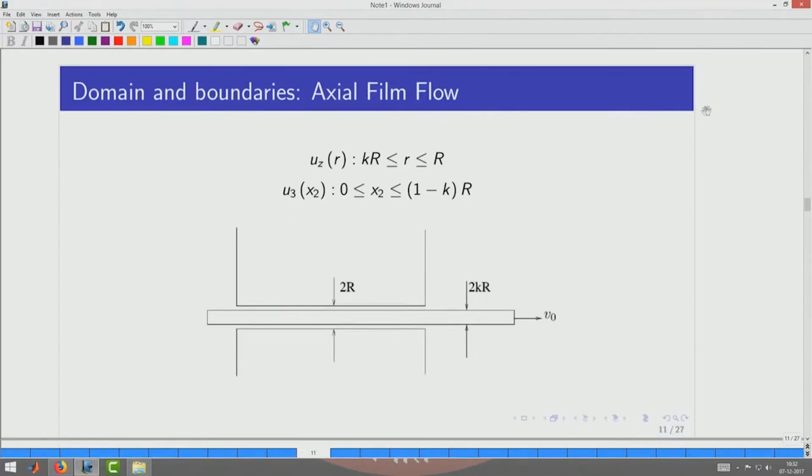So, here is one more problem to look at. You can see that here we are looking at the flow in an annular tube. So, where is the liquid? The liquid is here. So, it is in this annular tube, okay. If you now look from the side, the liquid is here in the annular region, okay, and it is flowing in this annular region because the rod is being pulled out. Because of this, the liquid in between the shaft and the annular hole is moving in this direction, the direction I have indicated.